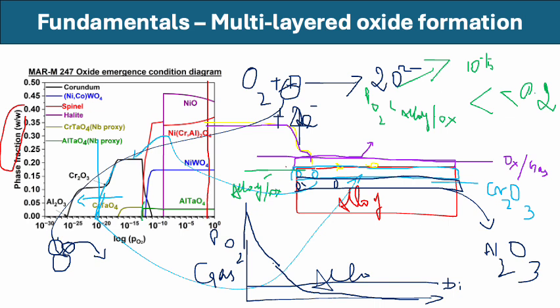But up to this distance, you have oxygen partial pressure that is above the aluminum oxide formation level, which means that even though, let's assume a case where we do not have enough aluminum to form an alumina scale on the outside, an external scale, in this region you start to form some alumina particles as an internal oxide. This internal oxidation is detrimental to the mechanical integrity. So that is also a result of this oxygen partial pressure.